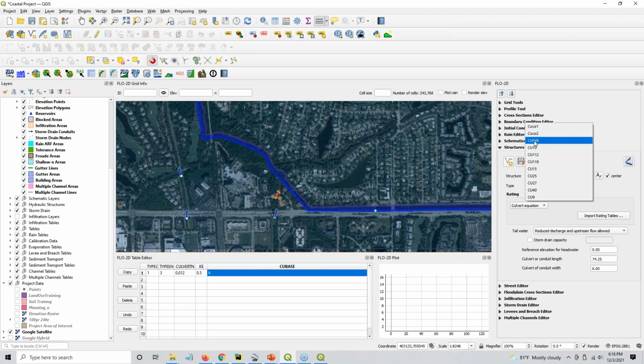So a couple of things that are important. If you're going to be putting these structures in, it is probably a good idea to name them 001, 002, N, because if you have several hundred of them, QGIS tends to sort things literally, and it will sort like the 1 right next to the 12.